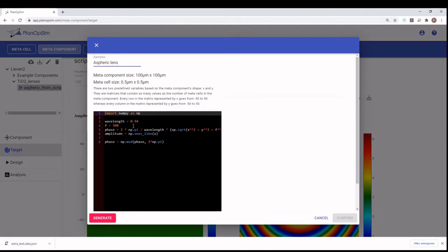which will then need to have two things set. One is the amplitude of the wavefront, of the complex wavefront that we're making. The other one is the phase. And on top of that, there are some parameters to set in this case, but this is completely free, of course, in what you choose to define. So let's make a lens with a focal distance of 100 micron and give it a circular shape also. So I will make a mask here, a circular shape.